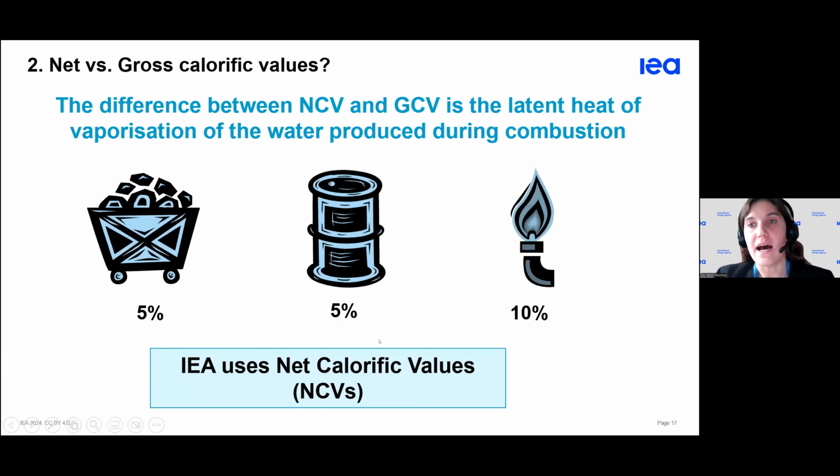So this means that when calculating an energy balance, you need to make sure that all fuels are not only in energy units, but in energy units on a net calorific value basis. The biggest example of this is natural gas, which in the commodity statistics is reported in terajoules gross. So we need to convert this to a net calorific value basis by applying the standard 90% conversion.